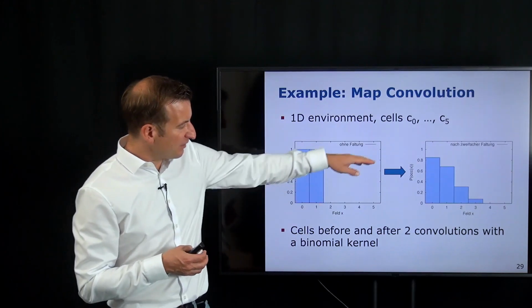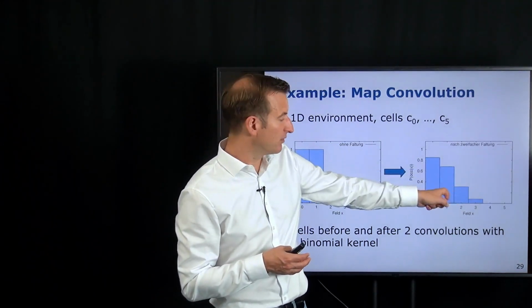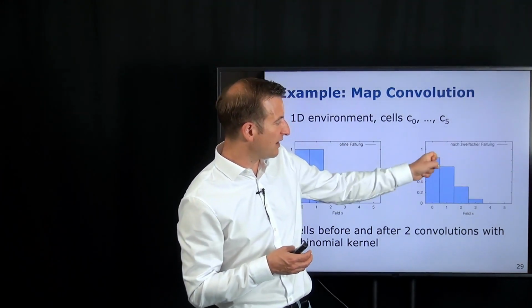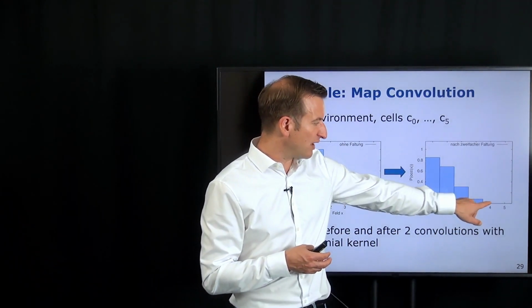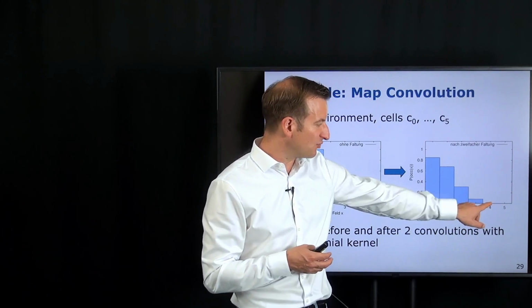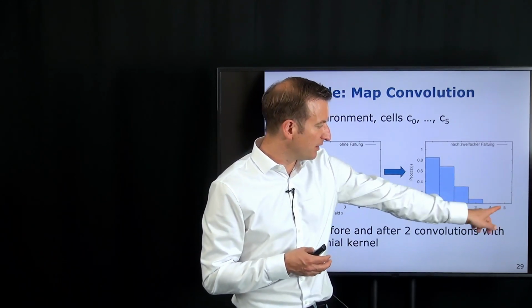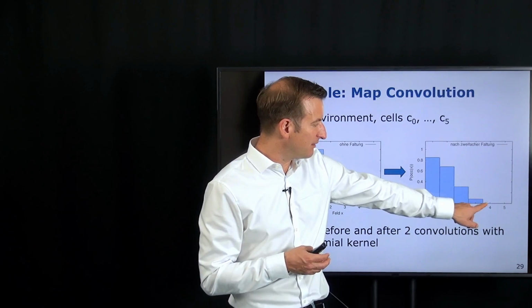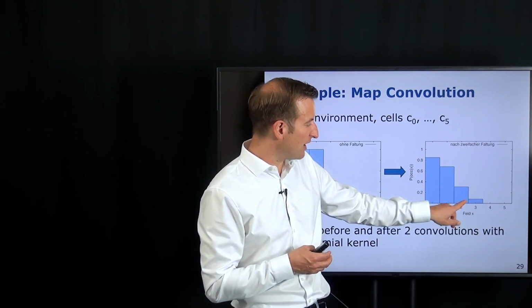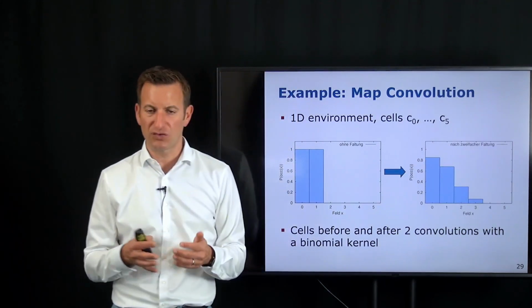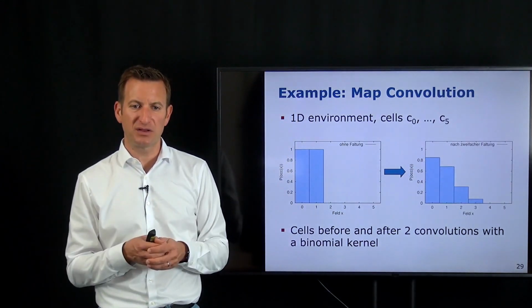If you see the probability as cost, the higher the probability, the higher the cost, then the robot would try to stay away from the obstacle, maybe drive in this direction around grid cell 4, but if it can't do better, it would drive on 3. If this still doesn't give you a solution, it will drive on 2, and so on and so forth. So it would try to keep the distance to obstacles.